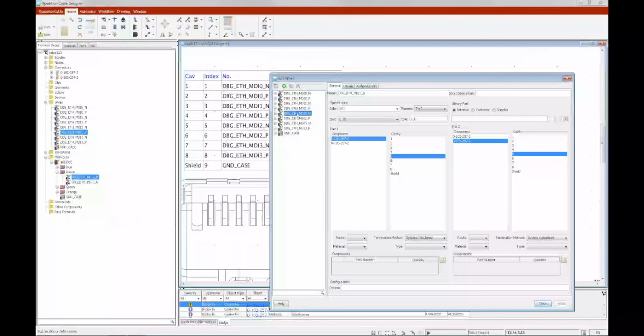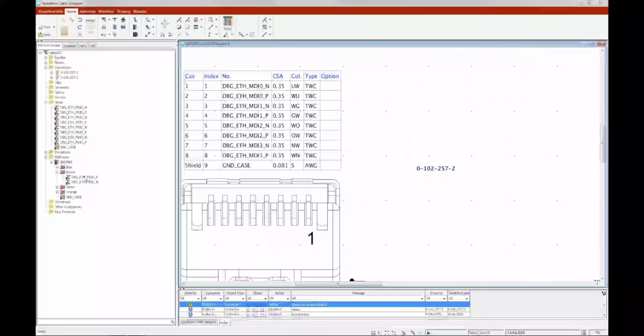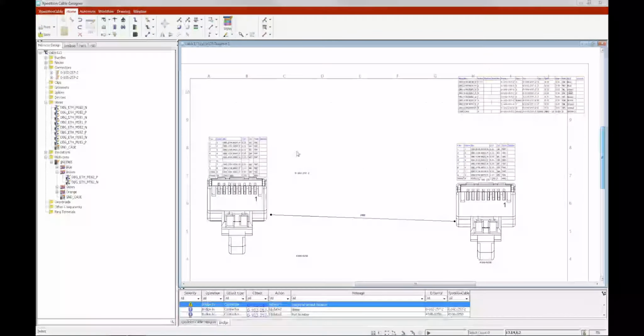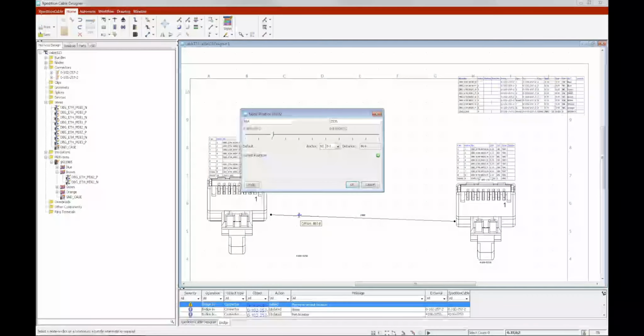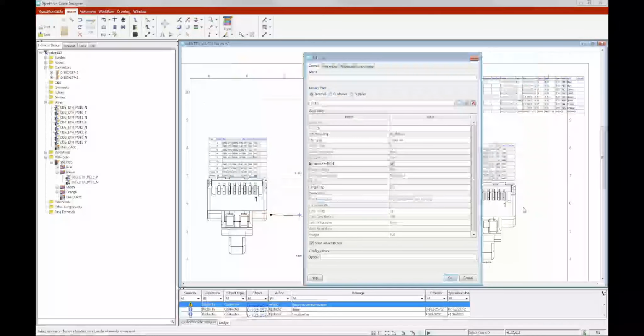Although a bundle has been assigned, the wire colors are not in the cavities, so the next step is to assign the wire colors to the correct cavity. In most assemblies, wires are also neatly routed, which requires retaining clips and mounts. Cable Designer allows the assignment and position placement of these clips.